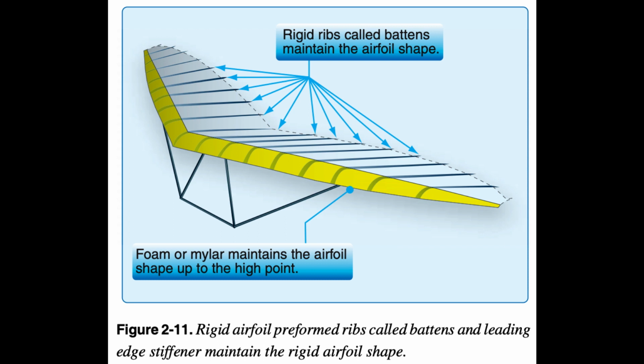Second, the wing is designed to flex as it changes twist from side to side for turning, historically known as wing warping. WSC wing warping is similar to what the Wright brothers did on their early aircraft, but they did it with wires warping the wing. The WSC aircraft uses no wires and warps the wing by shifting the weight, which is covered in Chapter 3, Components and Systems. This flexibility is designed into the wing primarily for turning the aircraft without any movable control surfaces like the ailerons and rudder on an airplane.